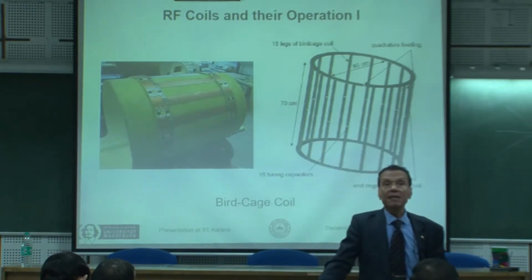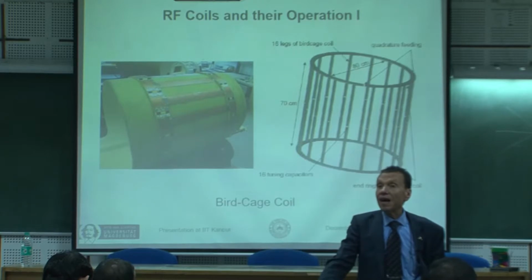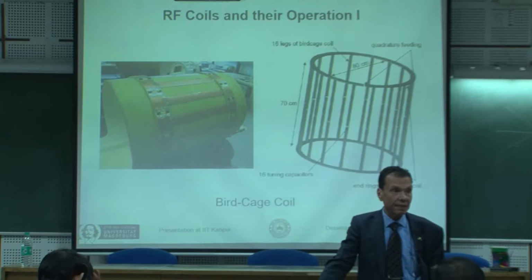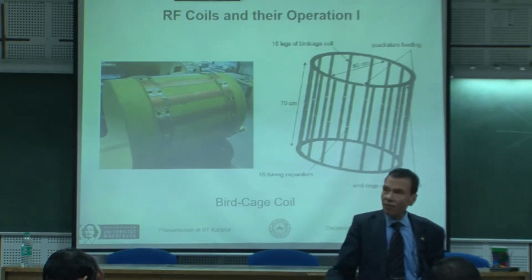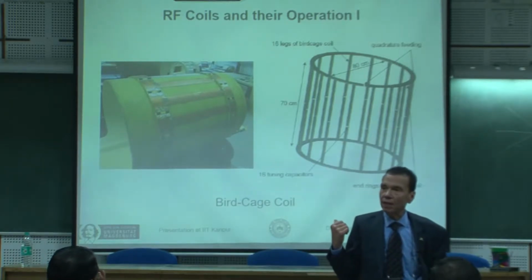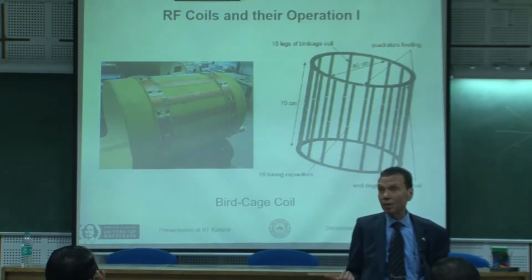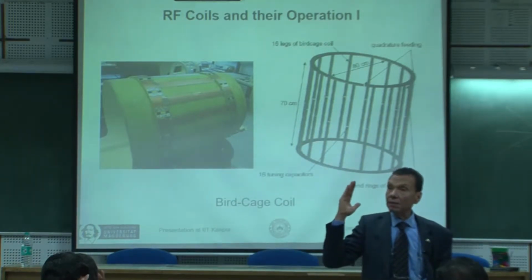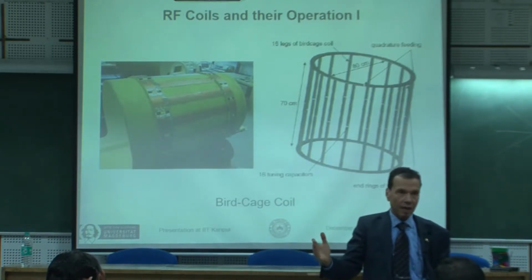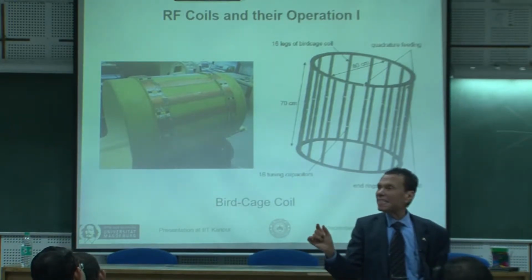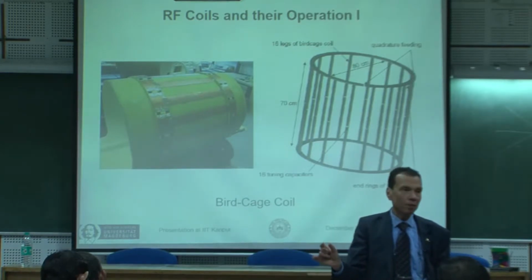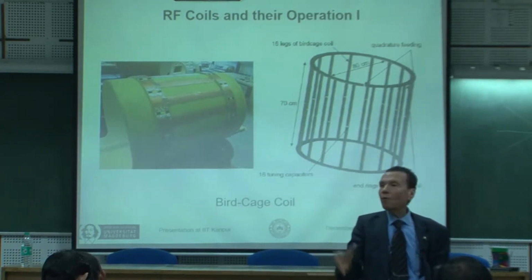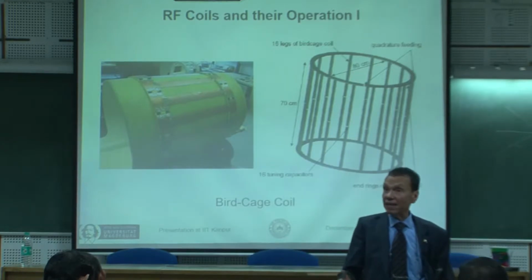Another one is the coil itself. If I have a high Q coil, I have a coil which produces a signal with high spectral purity. So one of the aspects in designing such a coil is to have it high Q, low loss. So I would like to have it around F0, which is the Larmor frequency, and with as little bandwidth as possible. But how little? Because you may have a very high Q.